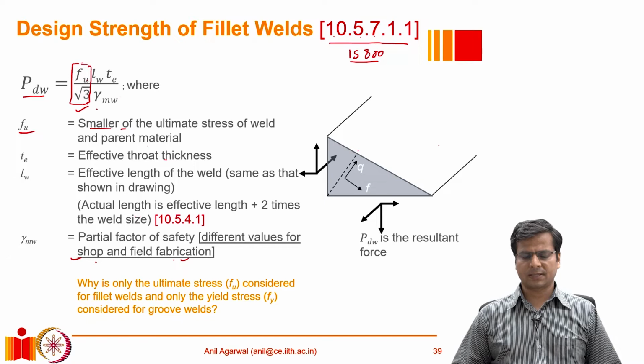So all the terms here make sense, and essentially what we are saying is that let there be any types of forces acting here, and they will be resisted by the other boundary. All those forces have to pass through this interface, so let us design this interface as if it is acting under shear, and calculate how much strength it has in shear, for whatever forces you are applying.